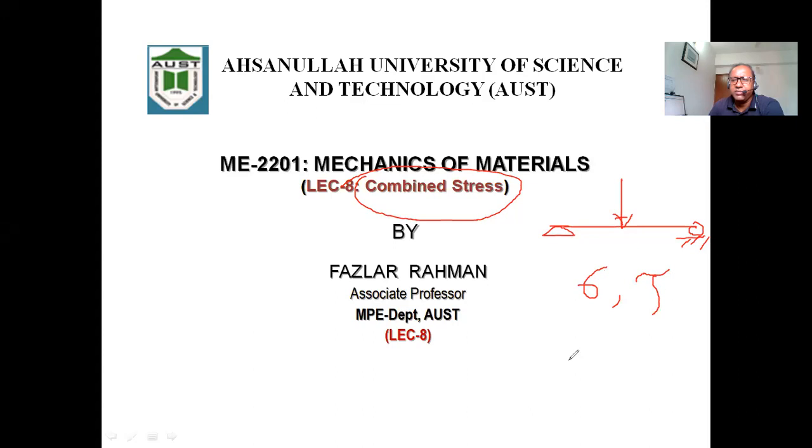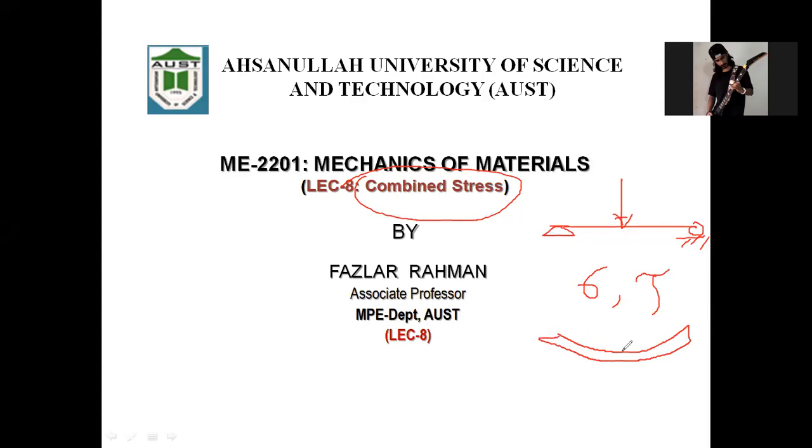And if this beam is a little bit thick, then it will bend like that, right? Yes, sir. If it is bent like that, what type of stress will be over here and over here? What type of stress will be here? Sir, the upper one is the bending stress and the lower one maybe shear stress. The upper one is compression, the lower one is tension. Okay, what's your ID? 18. Good. Okay. That means two stresses developed.